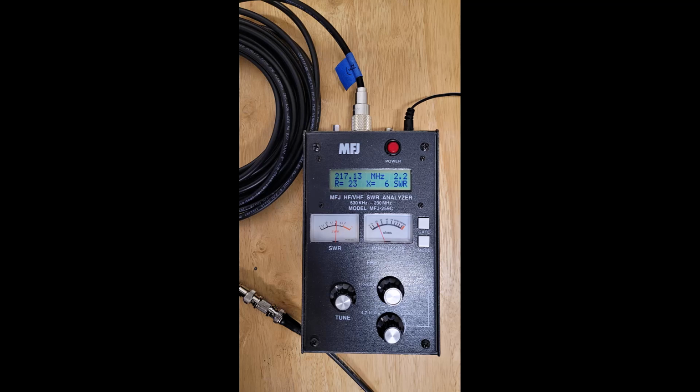And then the last question, which of the following can be measured with an antenna analyzer? Well, again, you can measure SWR, but that's not one of the options for this question. The other option that is correct is the impedance of a coaxial cable. You can set an antenna analyzer to measure impedance and read that off of the coaxial cable that's connected.